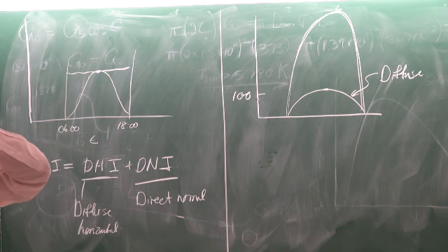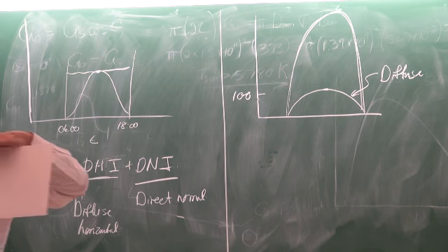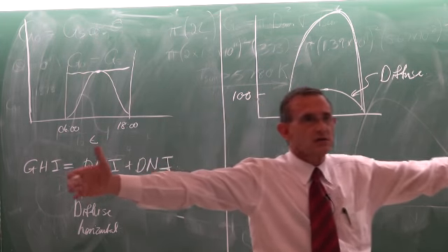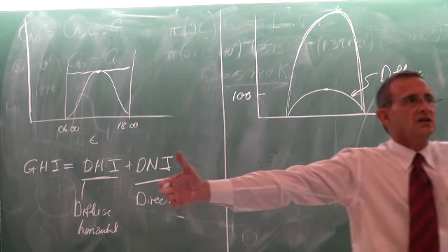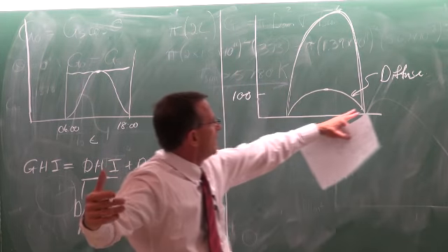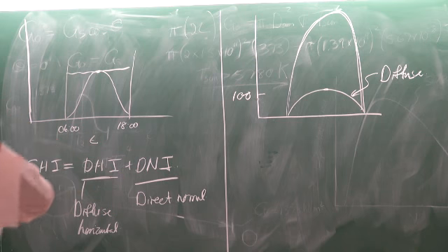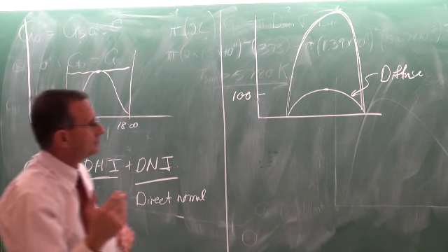Okay. Now the roof of Engineering 1 is quite high. Okay. So the reflection from other buildings is almost negligible. So the diffuse radiation is everything from the clouds in the atmosphere, approximately 100 watts per square meters.